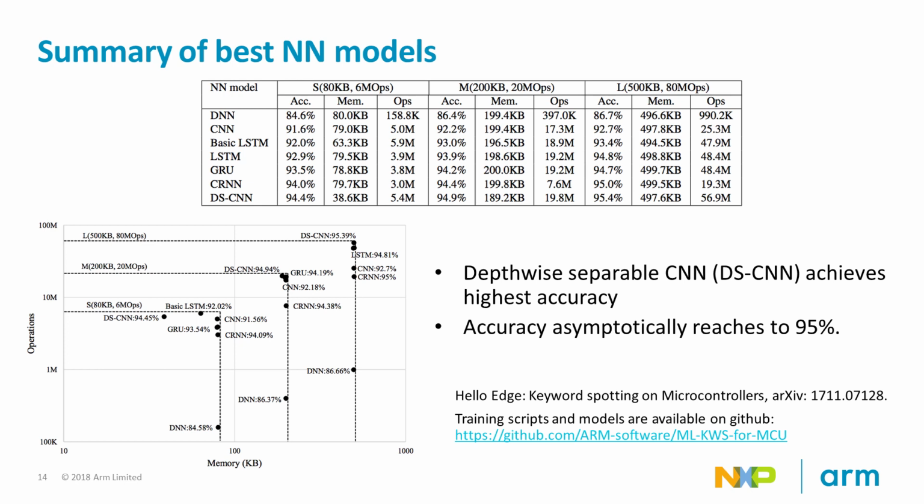Values are sorted into the charts and show, for example, that the DS-CNN provides very good accuracy of around 95%, meaning only 1 out of 20 spoken keywords is not detected, already with a very small network, while blending the lowest memory consumption of all test candidates with medium compute requirements. Only if you have very little CPU time to spare, maybe in battery-powered or lowest-latency environments, and a 10% lower accurate result is not an issue, the DNN is an interesting option. In the actual demo run, we will select this network now. We run this on the DNN variant.